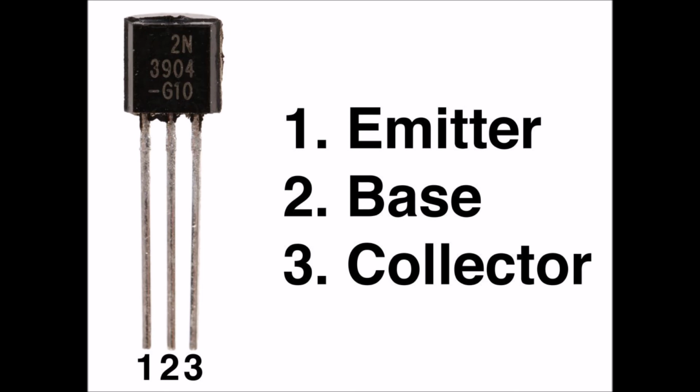The collector current depends on the emitter current and is independent of the collector voltage. The separation between the curves is quite uniform, which means that almost distortionless output can be obtained over the useful operation range of the transistor. Static forward current transfer ratio: the ratio of collector current versus emitter current when we place the base at electrical ground.